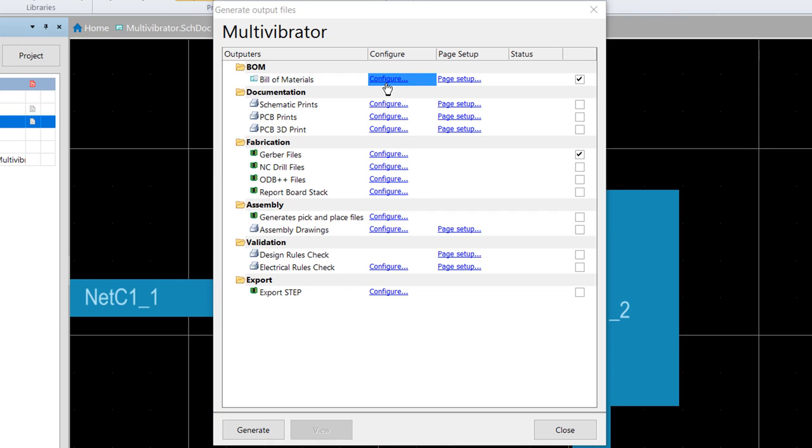Circuit Studio includes a highly configurable bill of material generation feature, which can generate output in a variety of formats, including text, CSV, PDF, HTML, and Excel. Excel format bill of materials can also have a template applied using one of the predefined templates or one of your own. Your bill of material output is configured in the bill of materials for project dialog, and since we